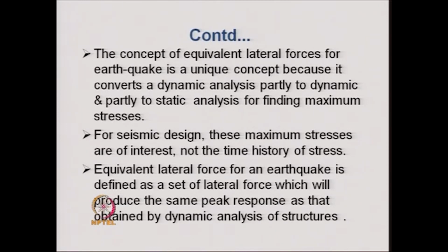The most important thing in seismic design is the maximum stresses that are developed in the members, so that the members can be designed for those forces. The designers really are not interested in the time history of the stresses, because the maximum stress is of direct interest to them. And this method provides directly the maximum stresses which are induced in different members due to earthquake.